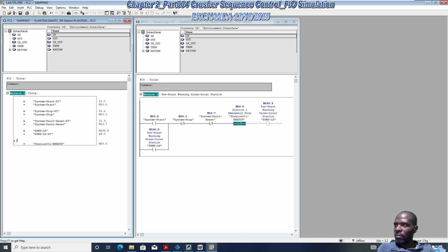And I1.2, was it 3? Okay, no, it's supposed to be I1.2. Okay, I1.2, pass your signal state to this bit address. Okay, like so. Save this, download.